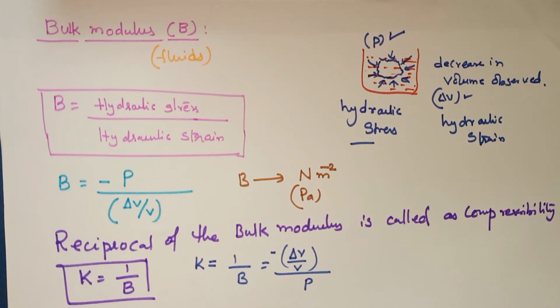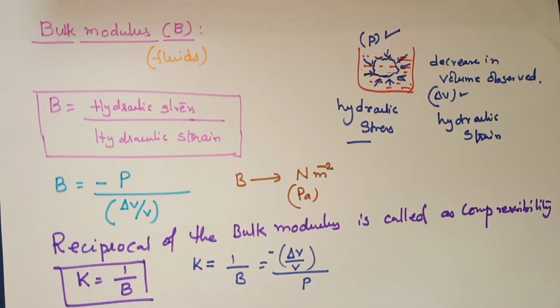Bulk modulus is more for solids than liquids. Bulk modulus values are less for fluids. At the same time, when the bulk moduli are less, compressibilities are more, so gases are more compressible. Gases are generally about a million times more compressible than solids, which may of course vary with temperature and pressure.